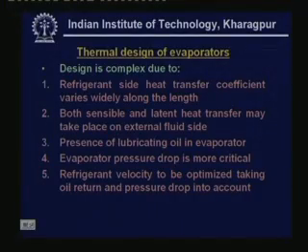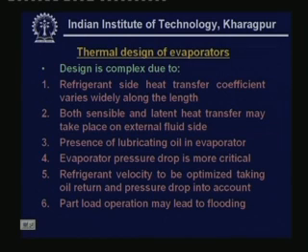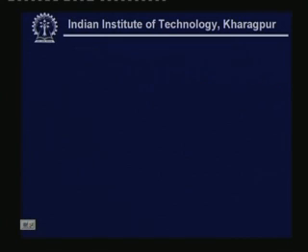As I have already explained, refrigerant velocity has to be optimized, taking both oil return and pressure drop into account. And finally, the part load operation may lead to flooding of the evaporator, which may lead to slugging of the compressor.